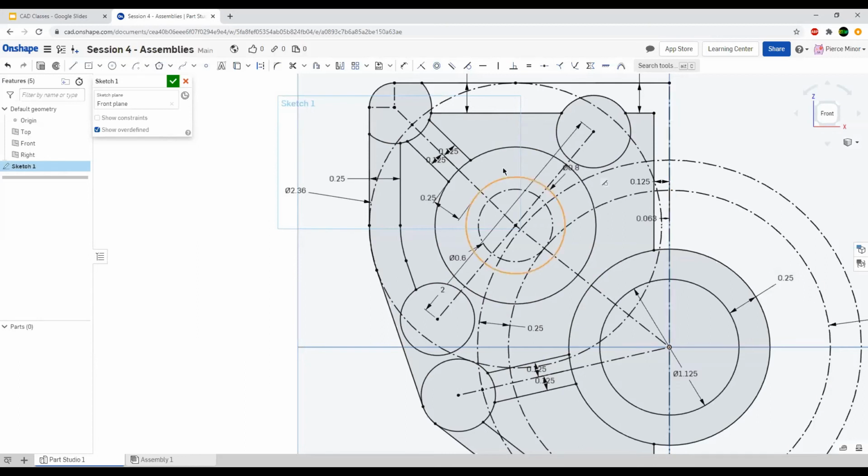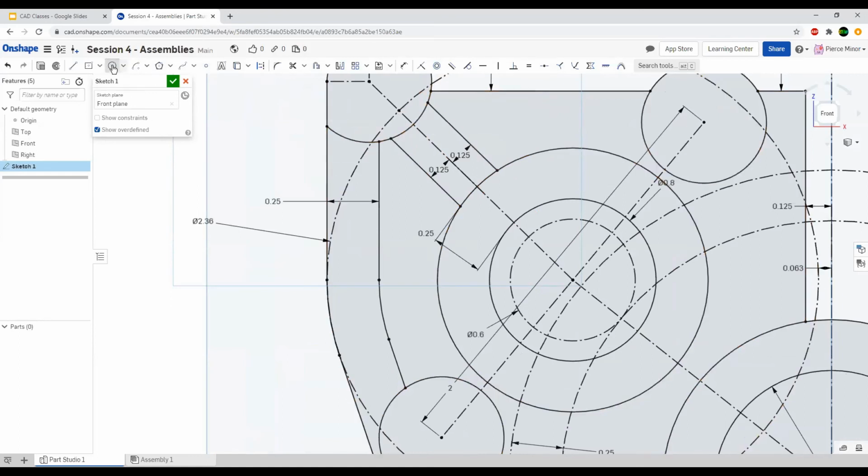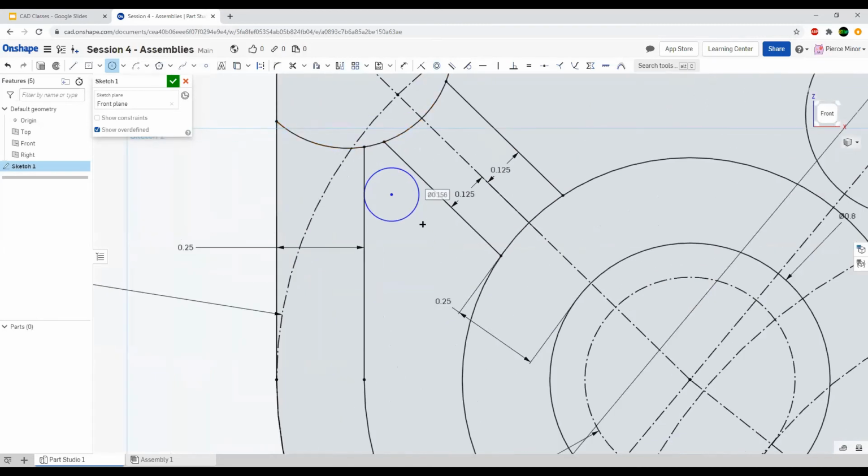So anyway, I am going to show you how to make a nice rounded corner. We're going to start with a circle. We're just going to drag it out to this line. You'll see that when you drag it out, the line will be highlighted and the tangent icon will show up. This is good. We want that. We are going to click on that line. Then we are going to open up the tangent tool again, go over to this line here, and set that tangent. All right, so now we have a curve.